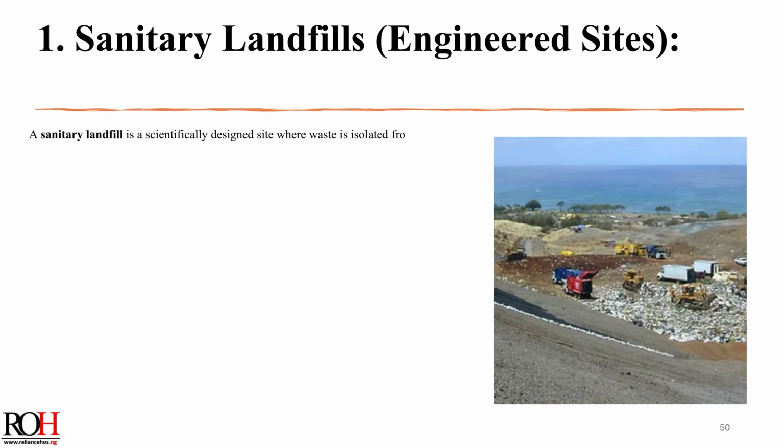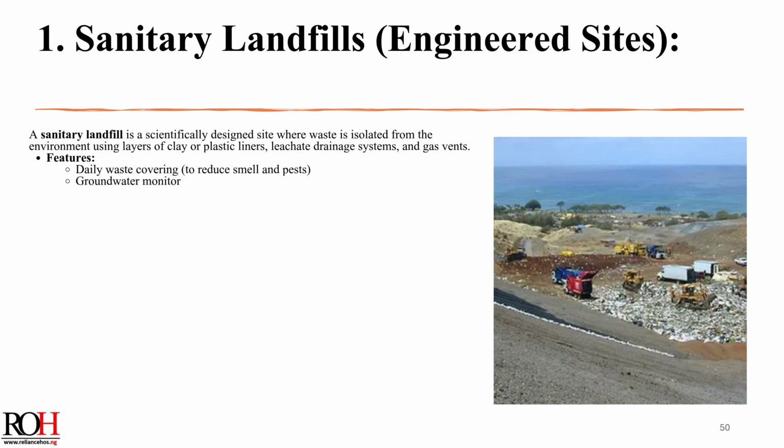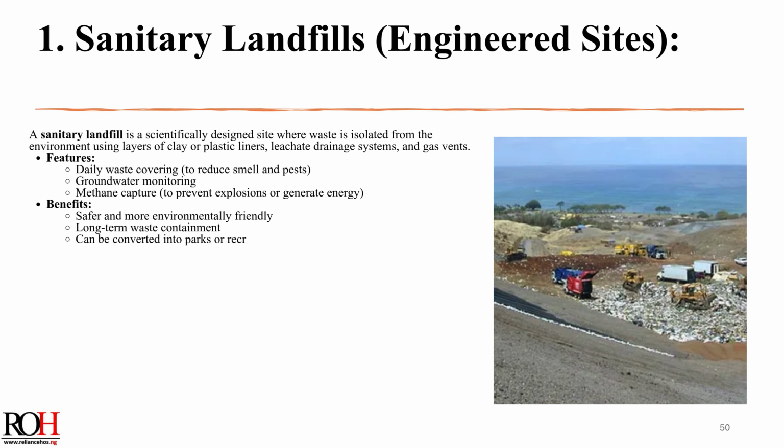1. Sanitary landfills. Engineered sites. A sanitary landfill is a scientifically designed site where waste is isolated from the environment using layers of clay or plastic liners, leachate drainage systems, and gas vents. Features: daily waste covering to reduce smell and pests. Groundwater monitoring. Methane capture to prevent explosions or generate energy.